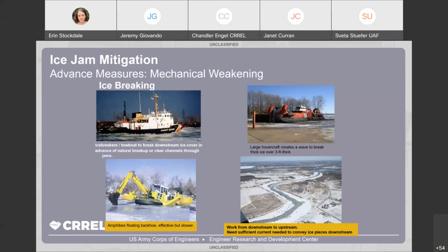Often we see larger scale solutions that are more effective, such as ice breaking ships. On the Mohawk River this year, actually, there was a new program using tugs to do some ice breaking in some slower moving water bodies within their lock system. And that seems to help significantly with a February breakup event this year in preventing an ice run from coming down that traditionally would basically be halted by this thick ice cover on a pool upstream of the dam. That ice ran through this year, and it's been attributed to the ice breaking activities by these tugs.